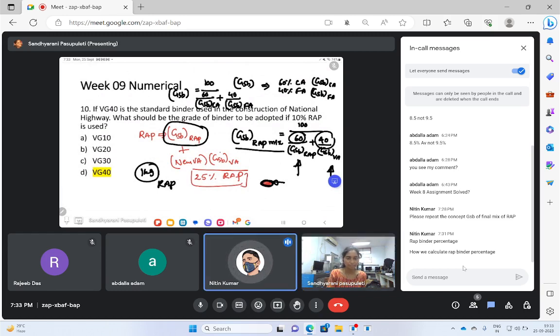Ma'am, which formula is used to calculate the RAP binder percentage? We do not have any formula. Usually we have to do the extraction and recovery process. From that process, whatever final binder you get, let us say you got 50 grams out of 100 grams of RAP, then 50 by 100 into 100. That is how you calculate the percentage.